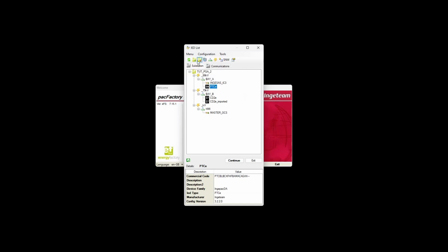Additionally, the CID exportation and importation functionalities are also available from outside the menu drop-down list. Next to these functionalities, the Export All CIDs shall be found, which allows us to select which CIDs in the installation to individually export. Next to the menu drop-down list, the Configuration drop-down menu shall be found. From here, the CIDs in the installation can be sent to an IED.